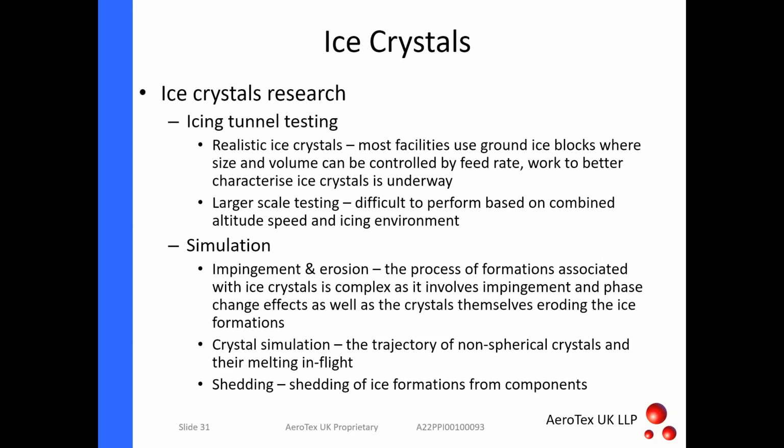And the crystal, so that's on the surface itself. The crystal simulations, these are non-spherical, as I said before, so they can go to different locations. And as they go into the engines or different components, they do start to melt. So you can get water forming around the outside of the crystal. And then, of course, the issue of shedding is how do we accurately predict when these blocks of ice are going to shed?